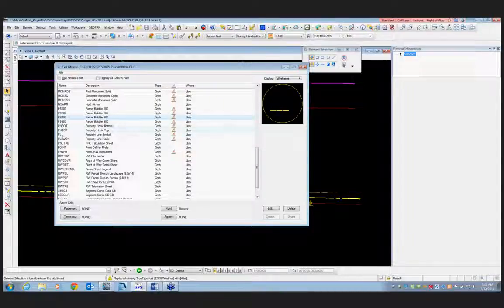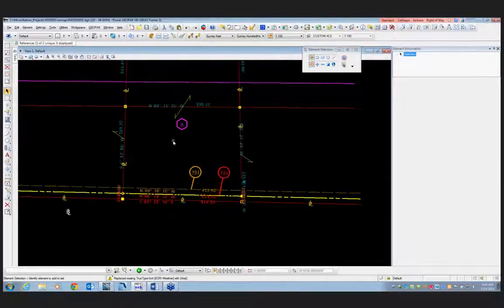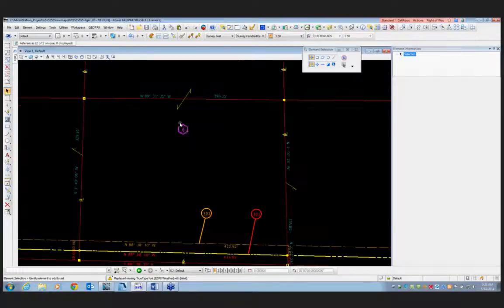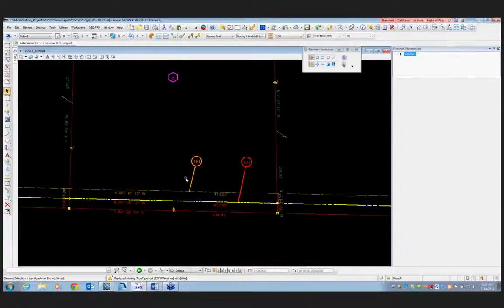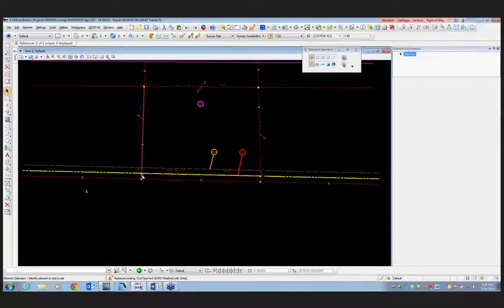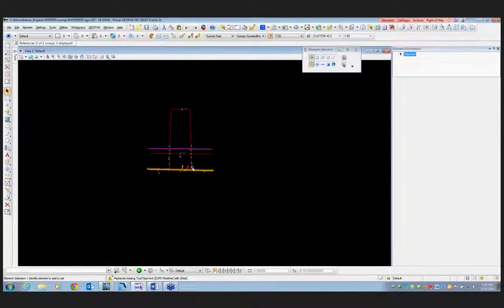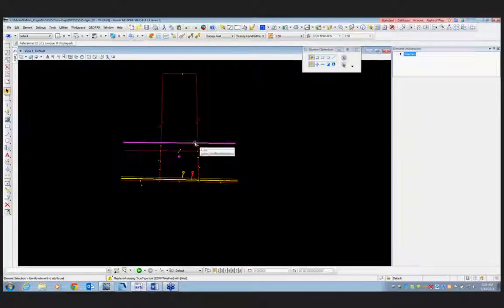Your property line symbols and your land hooks will also annotate. Here's another monument. So the monuments, land hooks, parcel bubbles, block numbers, things that you want to annotate will, the others will not. And as you saw, as I was changing it from a 2000 scale to a 100 scale or to a 50 scale, you can see how these cells will annotate. This can be very handy because what you can do is set up models and reference files that will take advantage of this.